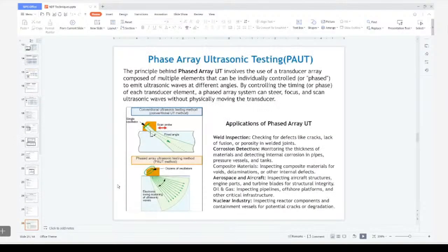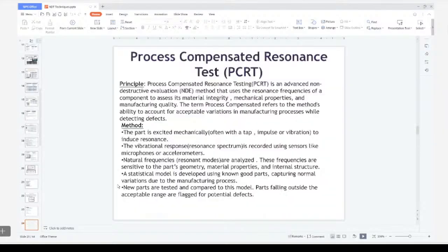Phased array UT is an extension of the conventional UT. So instead of having one single element of piezoelectric material in the transducer, I have multiple crystals inside. So I generate many rays of ultrasounds, which can be automated or optimized based on phase, time and amplitude. So I'll get the rays of a different range, which can be swept across a sample and get the information of the defects or thickness quickly in one shot.